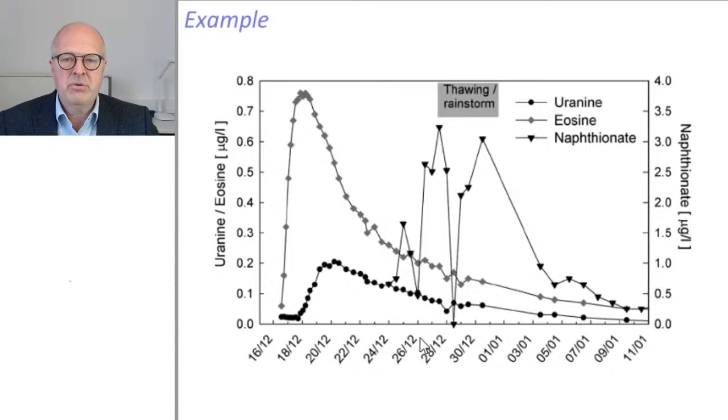And we had 3 possible sources that we considered, and each one was associated with a borehole, and I decided to inject uranine, eosin and naphthionate as tracers. We had a pre-experiment with pyranine that was quite close to the borehole, which yielded shocking results because the connection between the borehole and the spring was immediate, very, very quick, showing us that if this specific area was vulnerable, we would be in trouble.